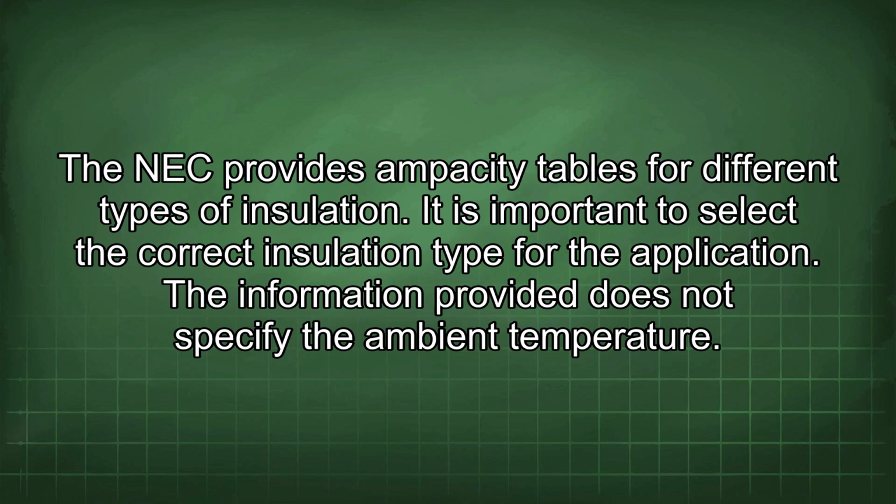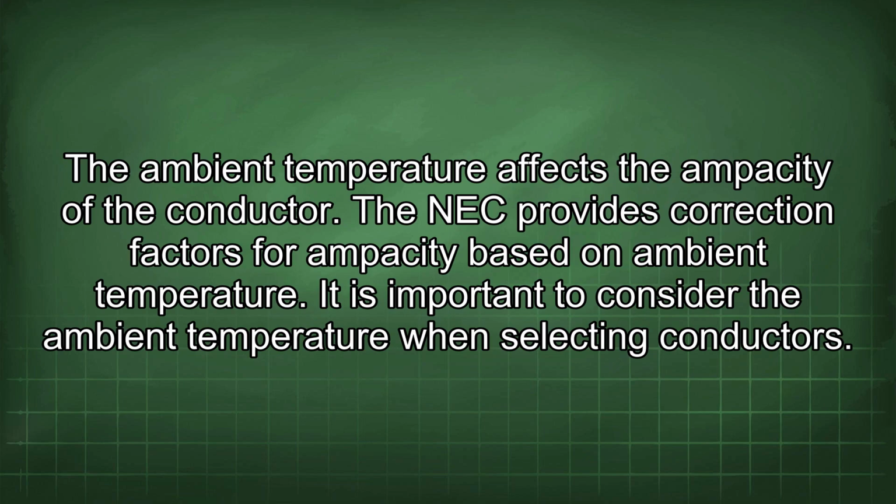The information provided does not specify the ambient temperature. The ambient temperature affects the ampacity of the conductor. The NEC provides correction factors for ampacity based on ambient temperature. It is important to consider the ambient temperature when selecting conductors.